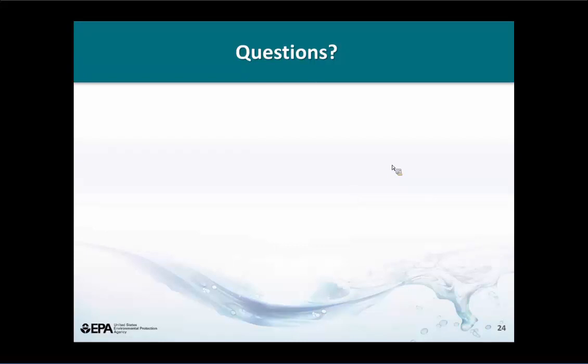Okay, and then the next question someone's asking is, can it handle a small agricultural sub-watershed within its network? Well, it can. In fact, we have a project. Chris Nietch, my colleague here in Cincinnati, took a HUC 12 watershed, and at first he modeled it with SWAT, as an agricultural watershed. And through the years, they started building a McMansion subdivision, which he modeled with SWMM. And then he and his colleagues are working on interfacing SWMM and SWAT.